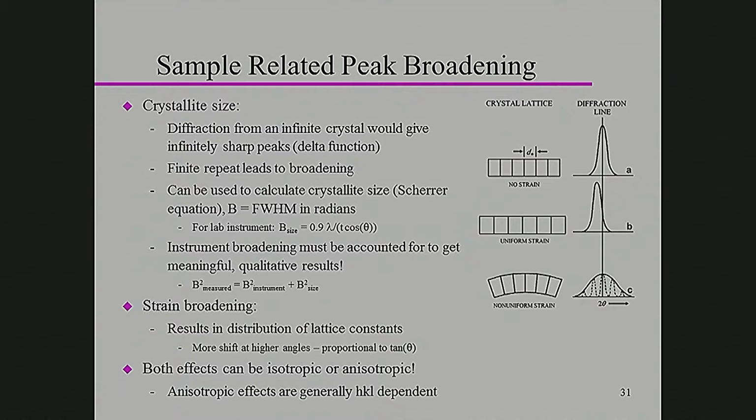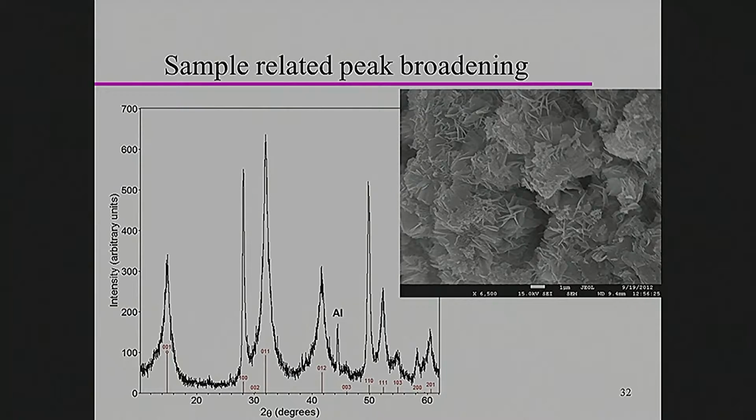Now, I did mention that these effects can be HKL dependent, and I have one very nice example that one of my grad students collected. She got this X-ray diffraction pattern, and there is one aluminum sample holder peak, but other than that, everything is matched by a single PDF card. If you didn't have that card on there, you would probably not guess that this is one phase, because some peaks are really broad, some are really sharp.